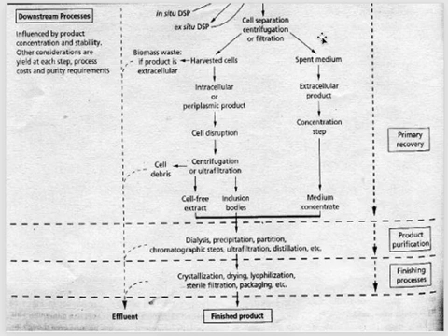But centrifugation is not a very efficient method if the volume is very high. Say you did fermentation of 1 lakh liters. 1 lakh liters is huge, right? Centrifuging 1 lakh liters is tremendous. It's tough, and the cost will be very high. So when you have to deal with a large volume of media, filtration is a better, more feasible, more cost-effective way.